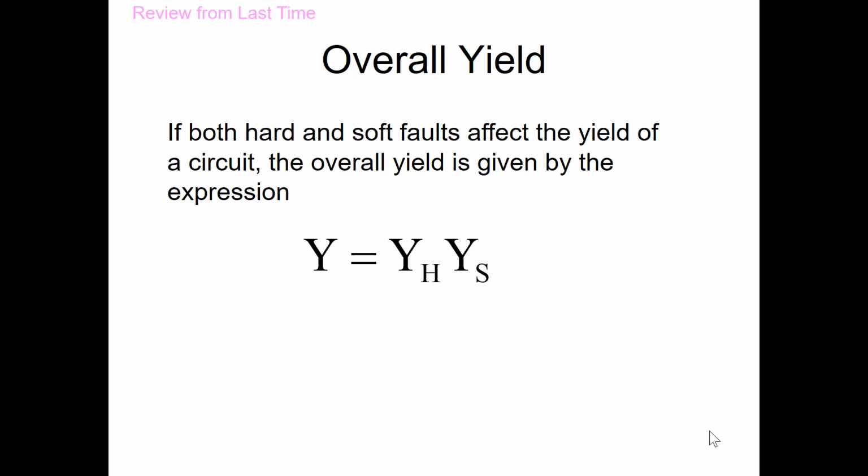And if you put transistors, ideally identical, on an IC, some will turn on at a little bit lower voltage than another would. And the turn-on voltage becomes a random variable. And if you're building things like an op amp, and you've talked about op amps in 230, offset voltage is one of the key parameters of an op amp.